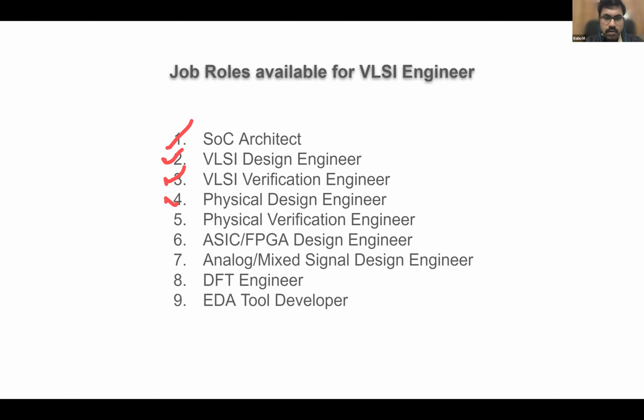Then the next role is the physical design engineer. He will be completely working on placement and routing, how efficiently the memory blocks as well as other blocks can be placed inside the available area. When the area is reduced, the transactions through the chip will also be faster. And if we have fewer interconnects between the devices and blocks, we can reduce the power dissipation also.